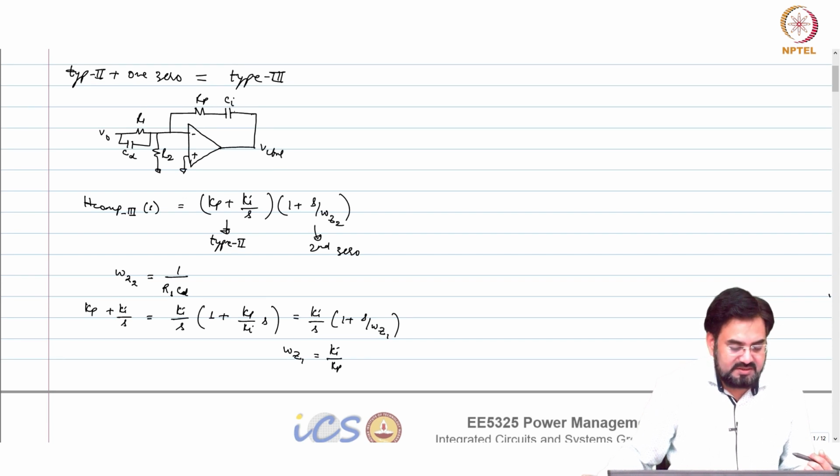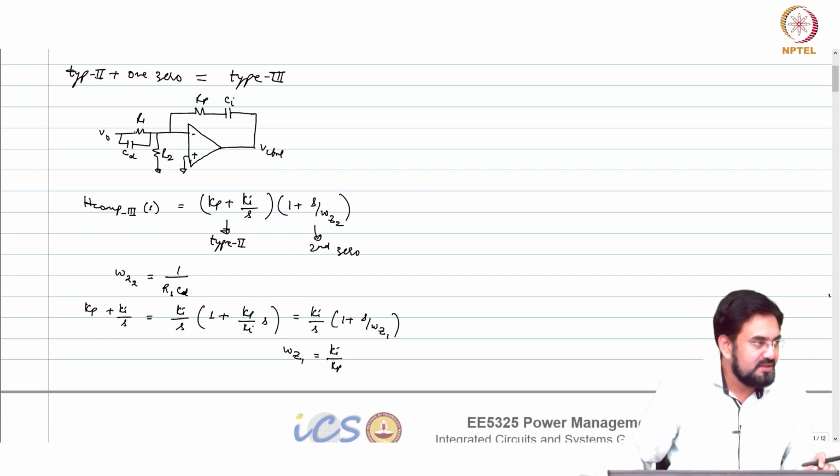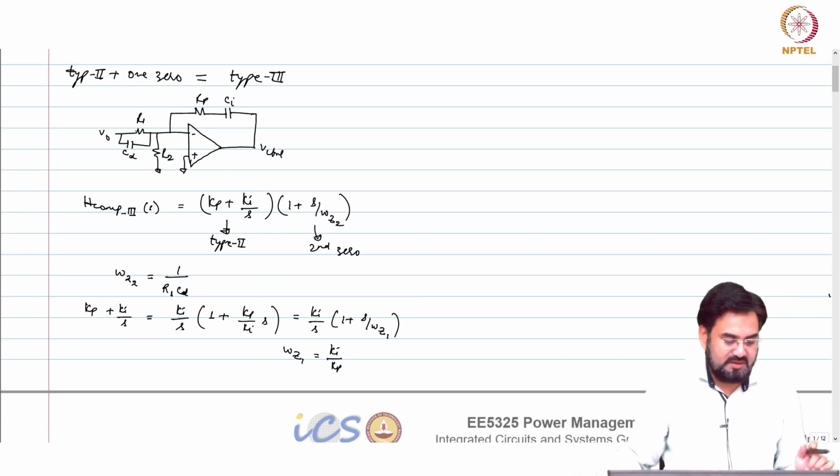after the first 0 appears, this capacitor will be considered as shorted. Okay. And what would happen to this? This cap is at a higher frequency. So, in mid band what you are seeing is minus Rp over R1. So, it is simply an inverting amplifier. Okay.